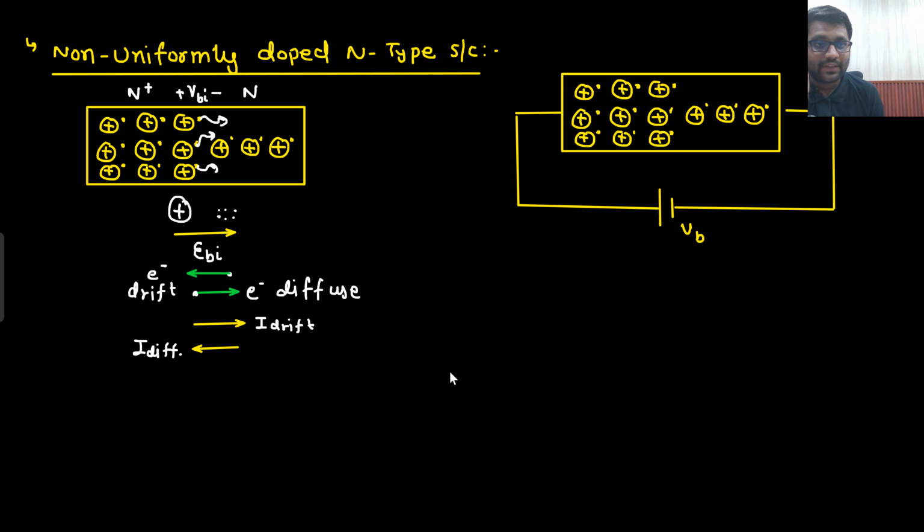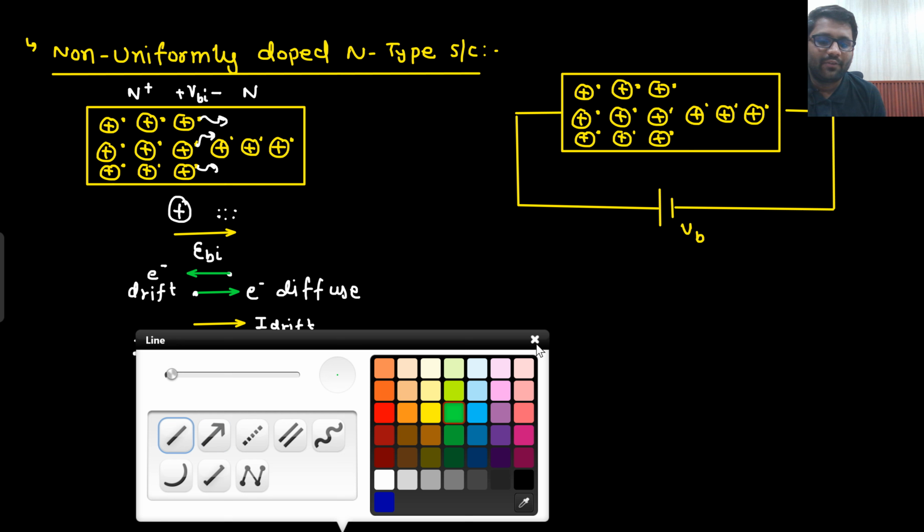And it is pretty obvious as well, because this is a semiconductor which has no external bias. If there is no external bias, that means it is under equilibrium. And under equilibrium, there has to be 0 current. So current is 0, but there has been an electric field that has been built up, that is E built-in. So what kind of energy band diagram were we making?